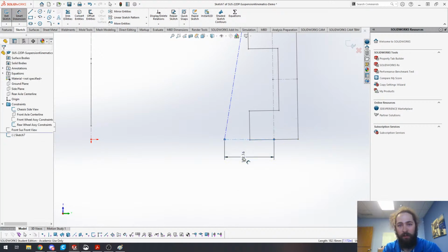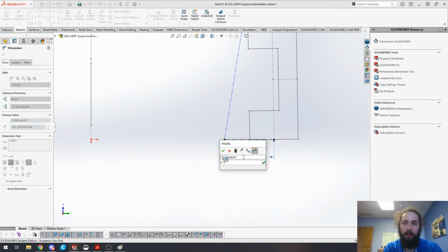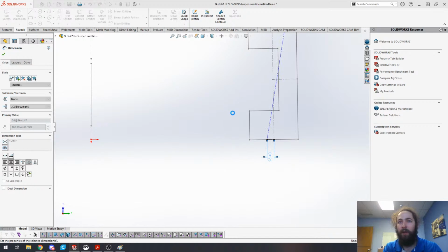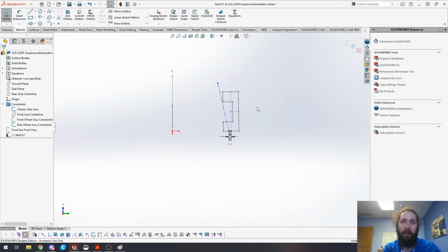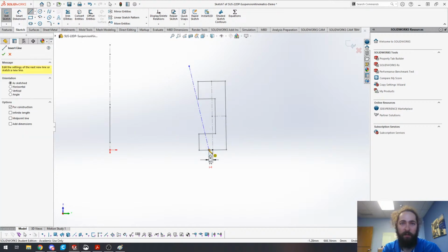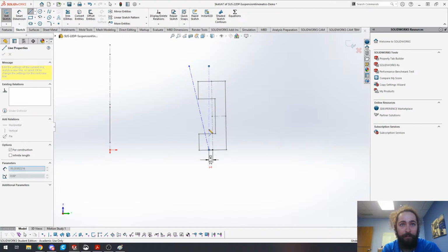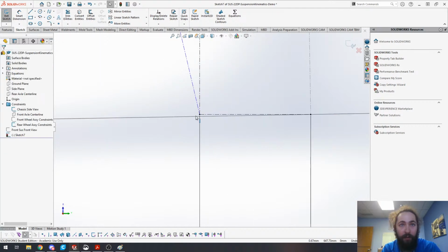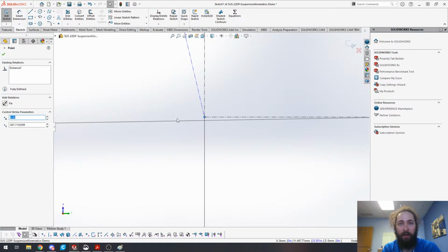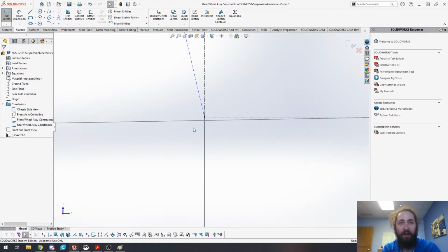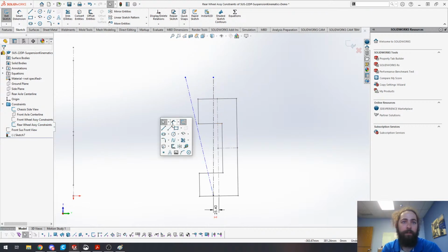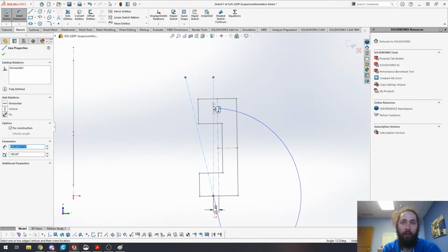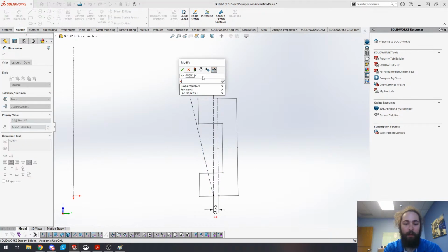This is still going to be our front scrub radius. We don't technically have a scrub radius in the rear because we're not steering the rear wheels in this case, which again, could also be a design decision that teams may want to go with later on. Okay, and this is something you always want to keep in mind: make sure that when you're drawing stuff here, you know what you're referencing. Cool. And then we'll do the same thing, kingpin angle. Everything is the same as the front.